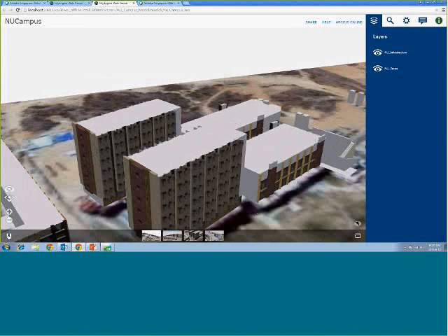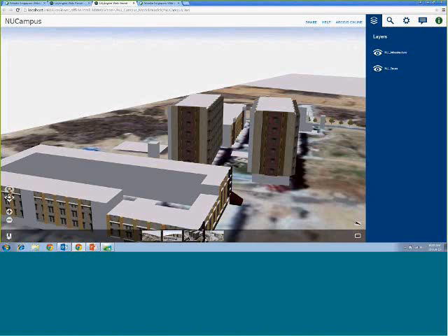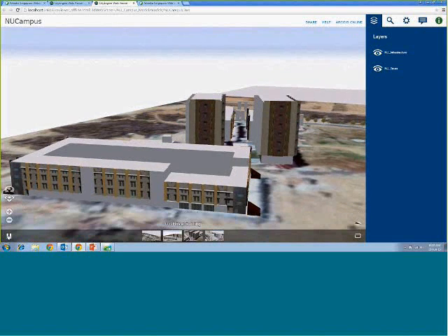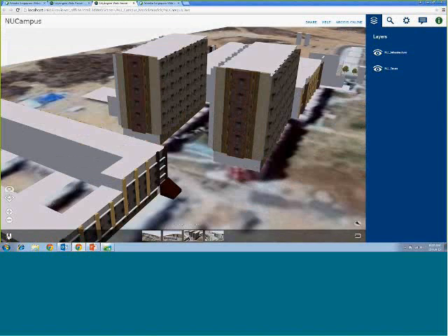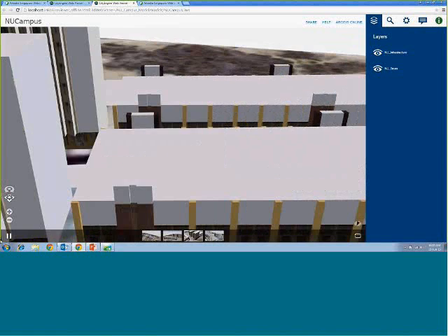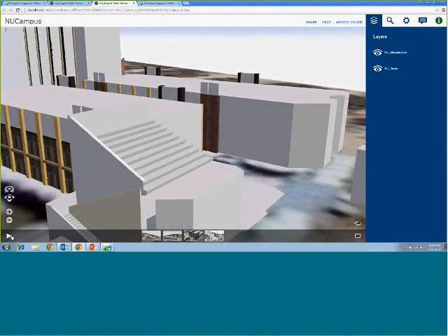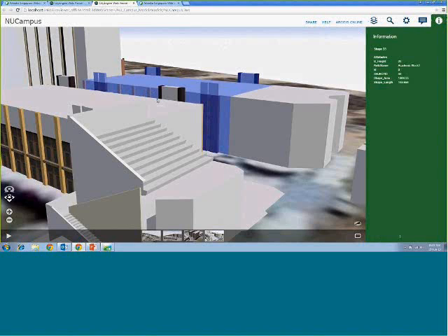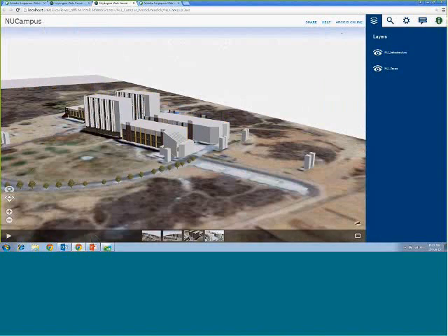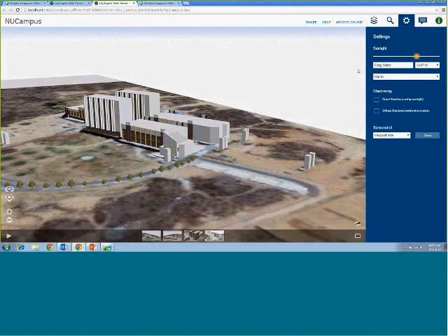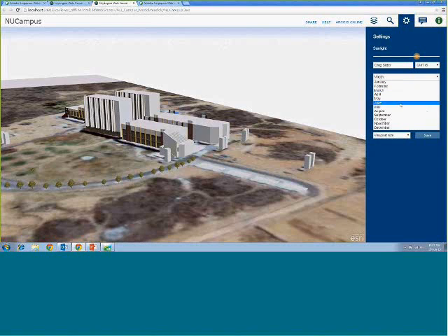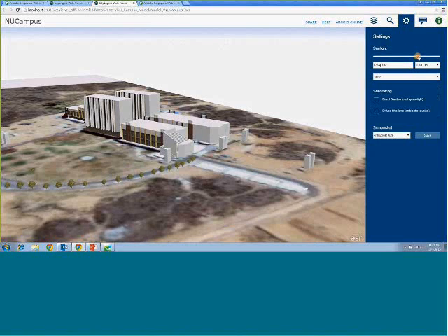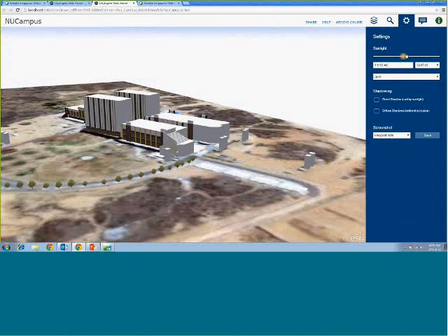One more thing which would be available with your web scenes is you may just have a sunlight effect on your particular cases. Selecting for June, I may see what would be the effect of light during different parameters. So this not only helps the users to analyze, they use these particular things so that they model the buildings in a way that every building gets maximum sunlight, or every building gets as much sunlight as possible, orienting your building or setting the setback accordingly.